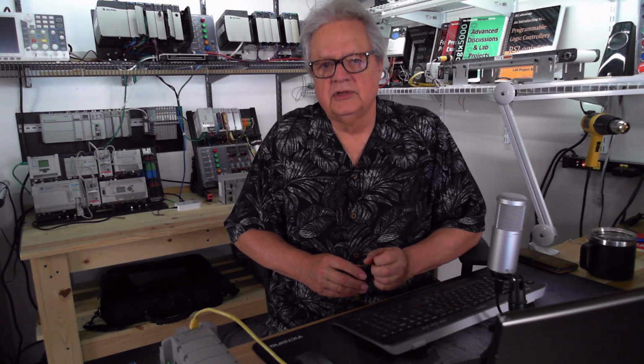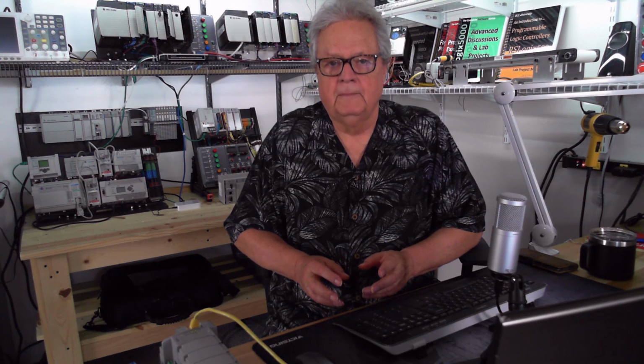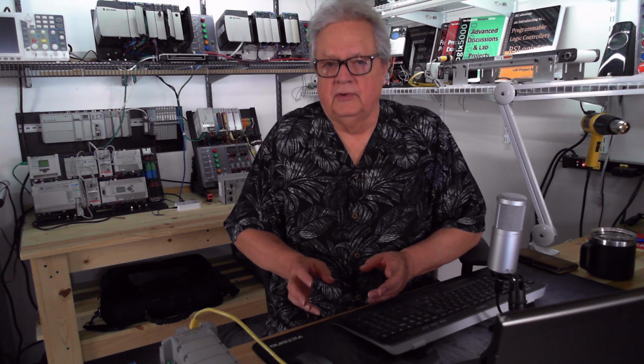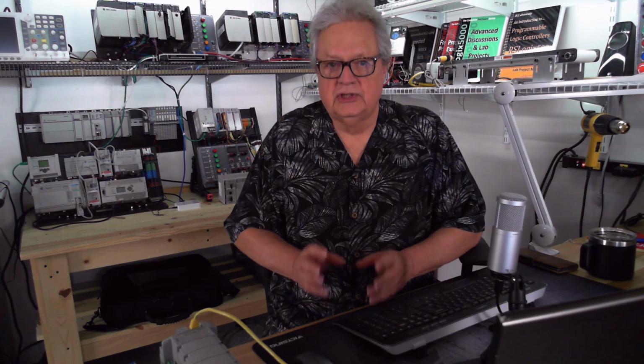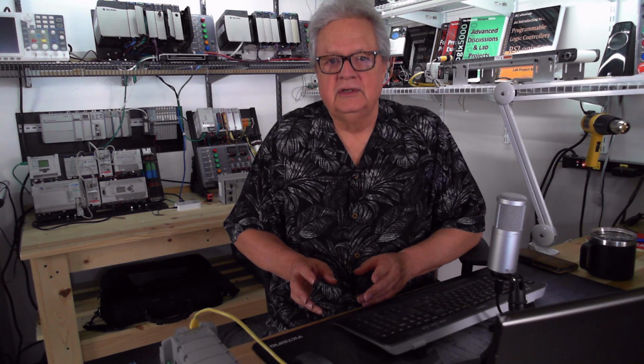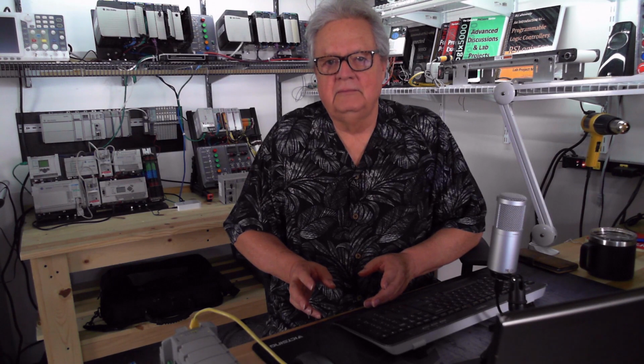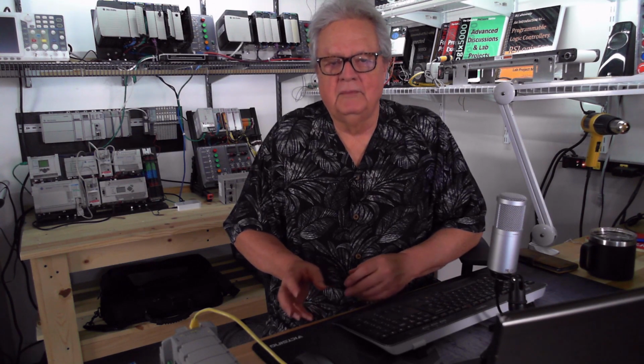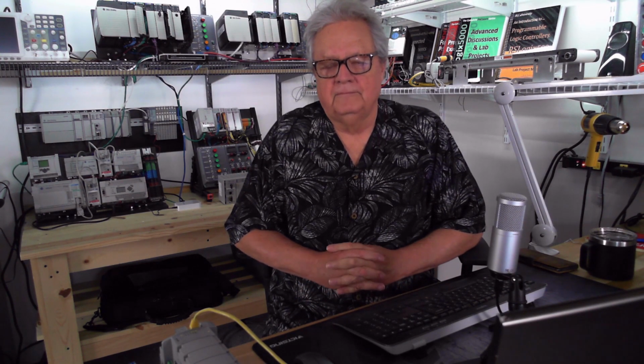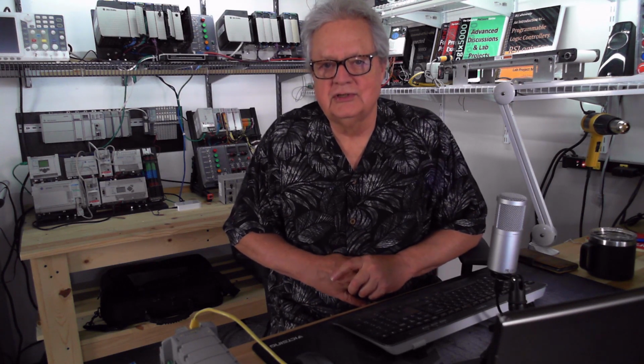I noticed it defaults quite often if I'm working with two screens and going back and forth, or if it goes into screensaver or the computer goes to sleep. So it's real simple. If it faults and you're still connected, just go up to diagnose and clear the fault and keep on going. Now when you clear the fault, it's going to leave it in the program mode. You're going to have to put it back in the run mode and back in remote. Or if it's not connected, then you go back to your program offline and download it. That puts a serious attention on whether or not you save your program enough.